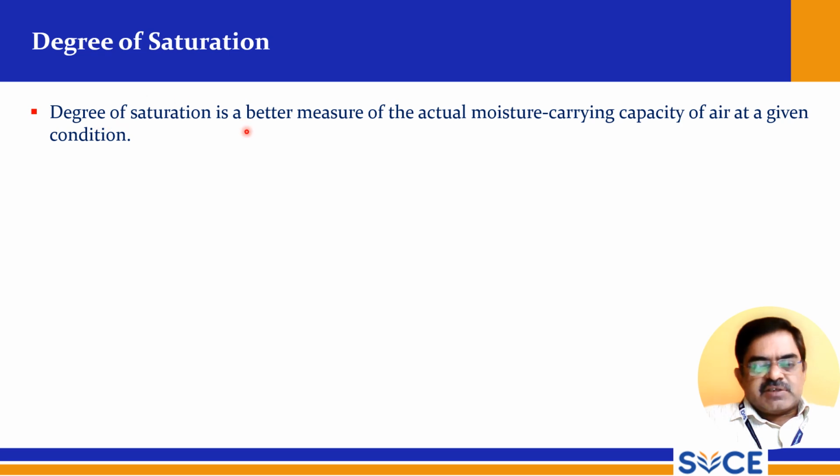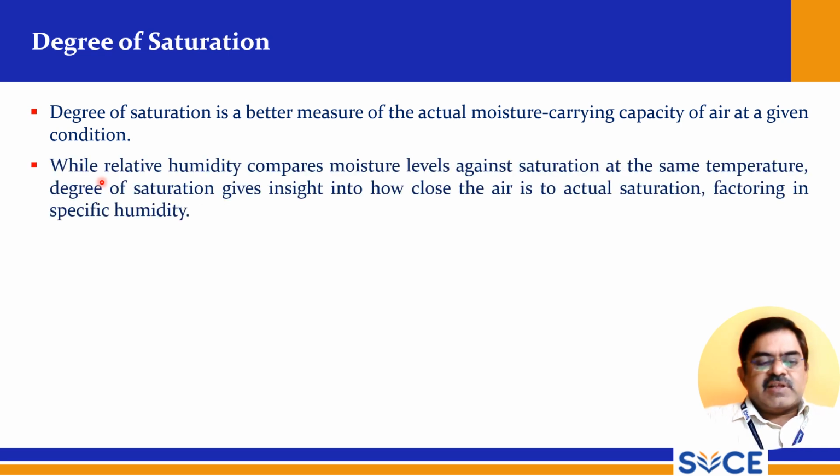Degree of saturation is a better measure of the actual moisture carrying capacity of air at a given condition, which is nothing but the temperature and pressure. While the relative humidity compares moisture levels against saturation at the same temperature, degree of saturation gives insight into how close the air is to actual saturation, factoring in specific humidity.